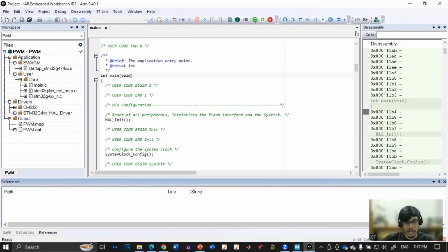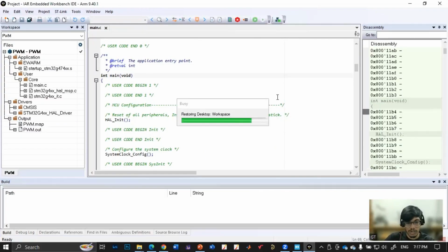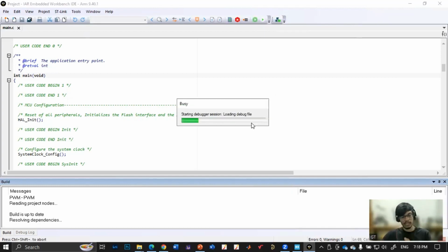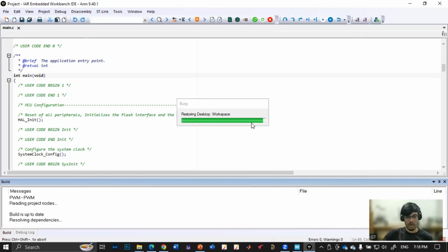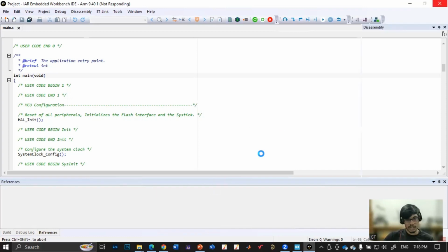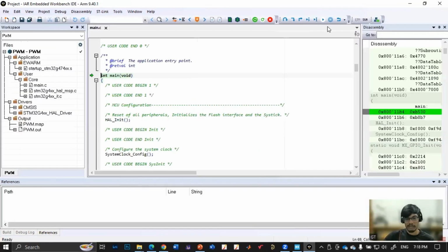Okay, so first, this PWM code is not inbuilt. This code is written, but I would like to show you the output of the code rather than how the code has been written. I just wanted to show you one example. Is this code for a buck converter? No, there is no buck converter. We are giving two gate pulses and we are seeing the gate pulses. They can be given to any converter. There is no dead time here. Yes, that is good that you pointed out that point. We will discuss dead time.